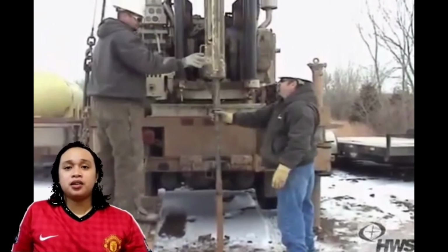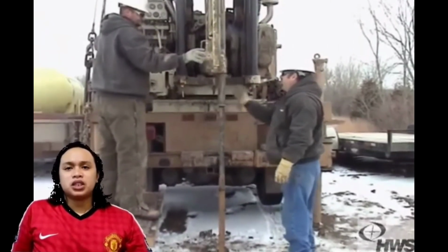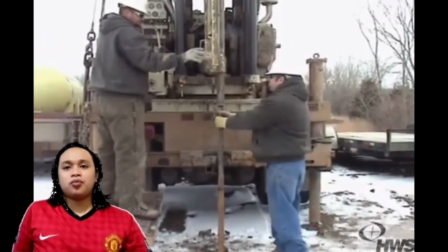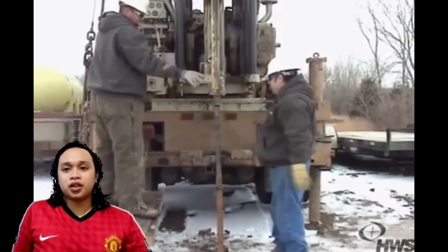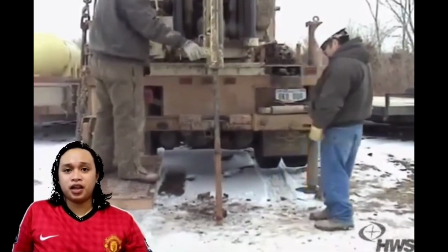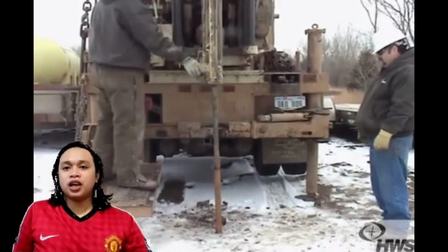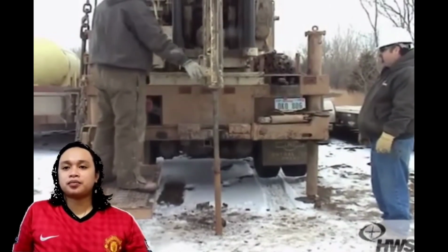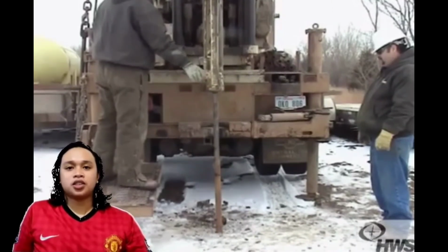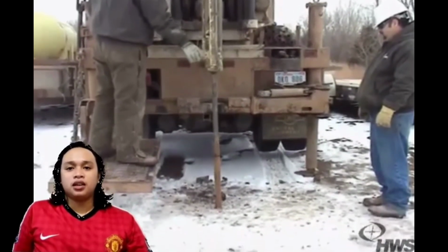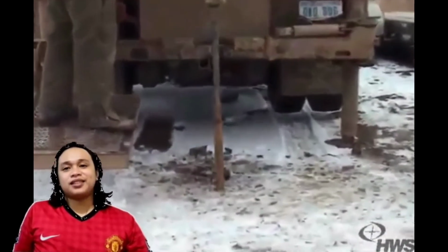This can be reasonably ensured by passing a rope over the pulley connected to the tripod head, letting the free end of the rope come down, and adjusting the tripod legs such that the rope end is at the testing spot.